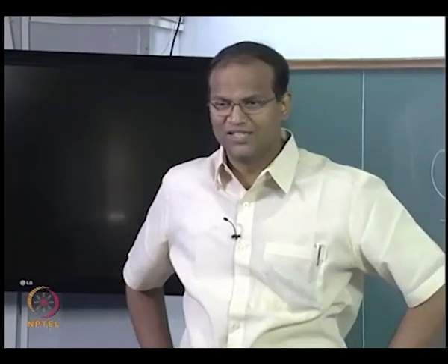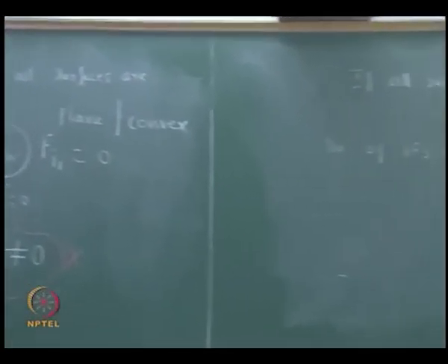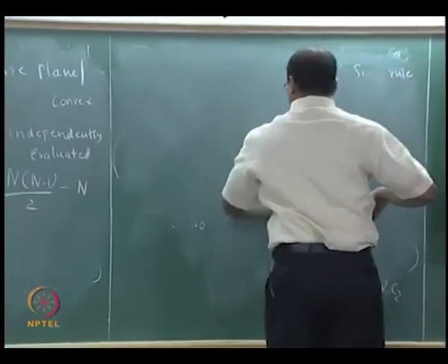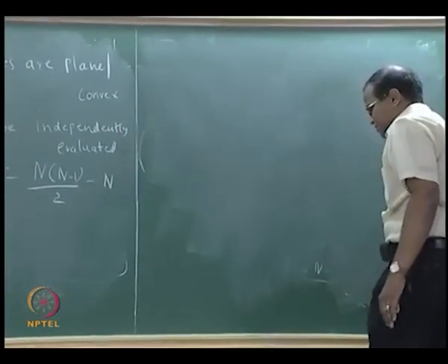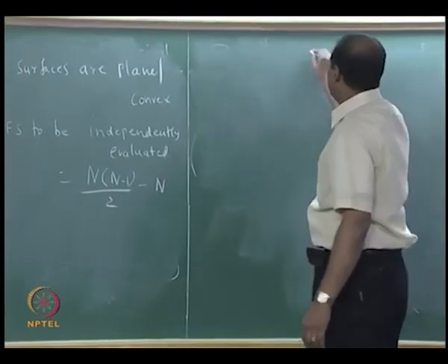Can you get those view factors now? Shall we look at a general triangular enclosure? Let us do that problem and close the discussion for the day. Which means you will write all algebraic relationships, manipulate them and get all the view factors.